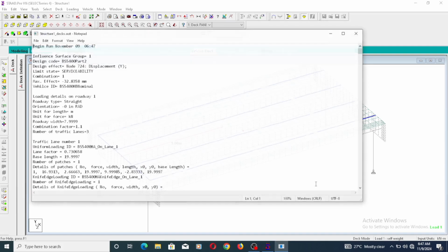In that note text, you can see the positions of our various loads, the number of national lanes, the forces, and every piece of information as regards the load. You can see our HB load is nominal HB. So once we OK this, it will be exported to our Staadpro model where we can make adequate load combinations.